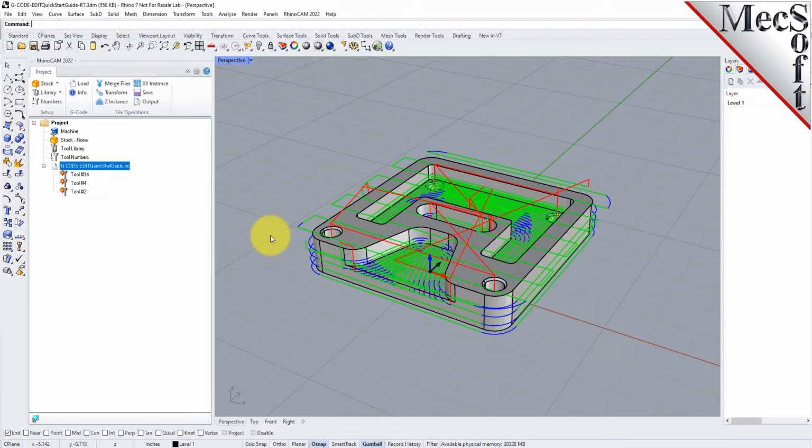That's because in your tool library, you may have multiple tools with the same tool number. In your shop, you may have hundreds of tools, following your standards for how you apply your toolpaths and your tools. You may have more than one tool with tool number 1, say.